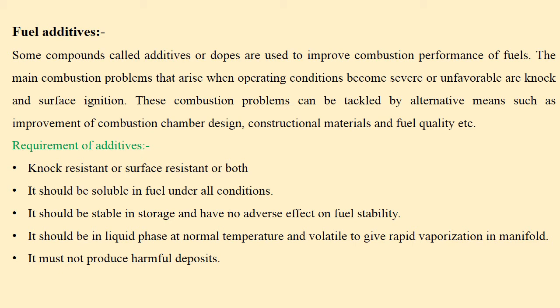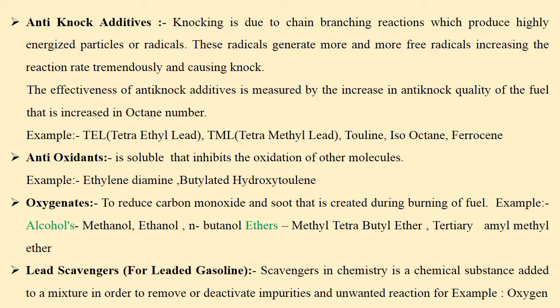So what are the different requirements of additives? In general, it should be knock resistant. It should be soluble in fuel under all conditions. It should be stable in storage, with no adverse effect on the fuel stability. It should be in a liquid phase at normal temperature and volatile to give rapid vaporization in the manifold. It must not produce harmful deposits. Likewise, these are the different requirements we expect from fuel additives.